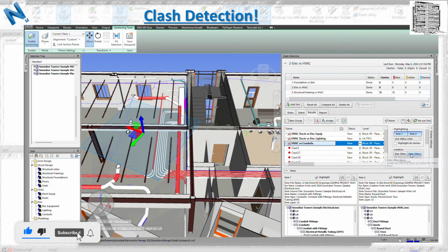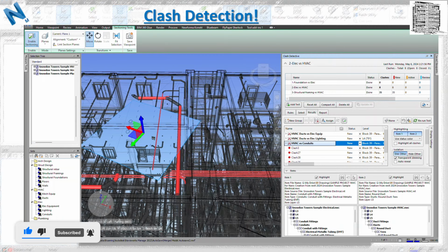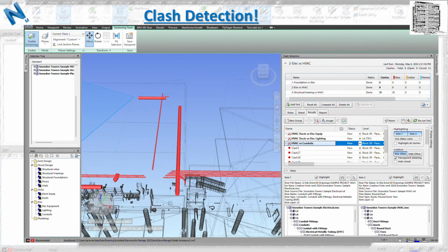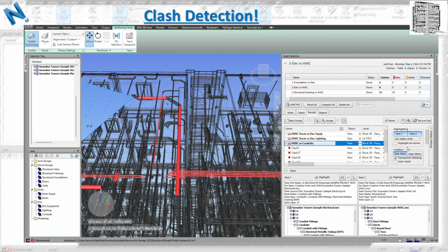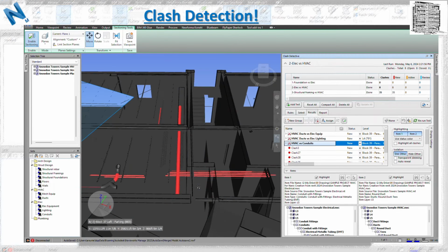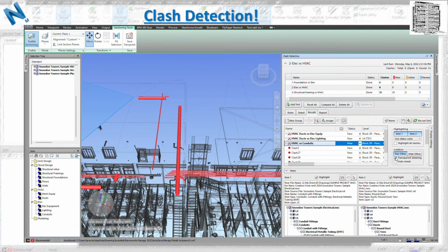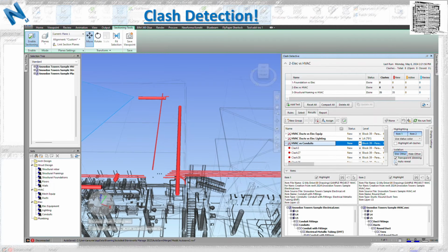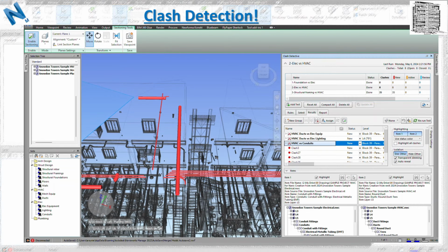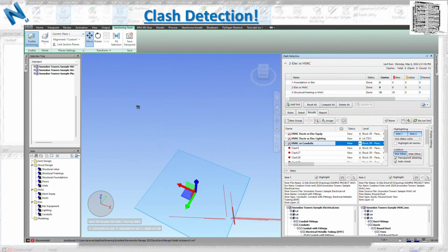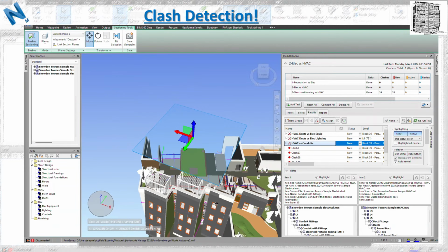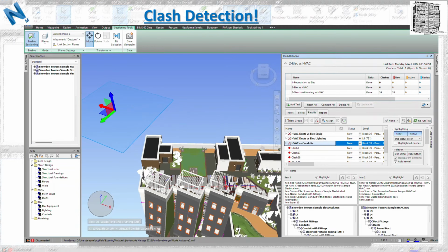If you want to dim other, you can see your clashes highlighted and everything is dimmed. If you uncheck the transparent dimming, it turns everything solid black, and only clashes are highlighted. Right now it's on status color. If you go to the item color and make it green and red. Auto reveal is basically, if you have a clash that is hidden, let's say under the slab or under the roof, you can find it. If you have that box checked, it reveals that area for you.